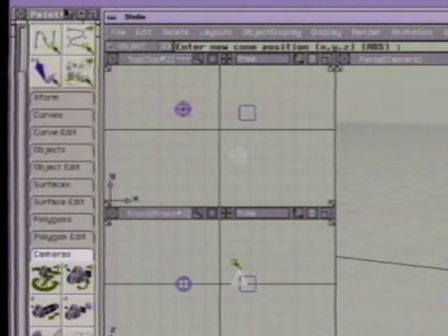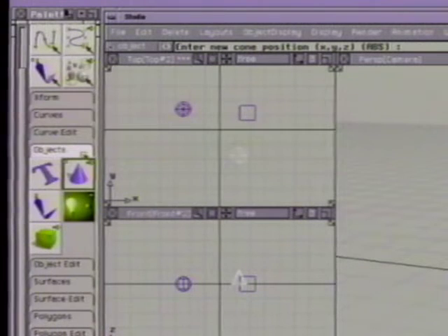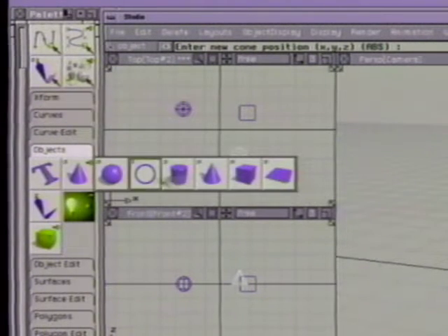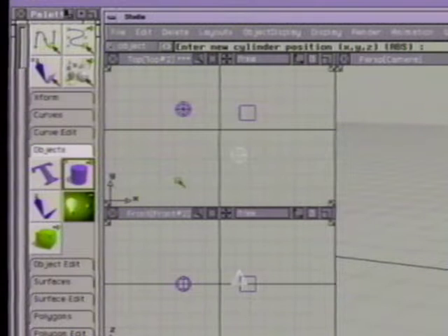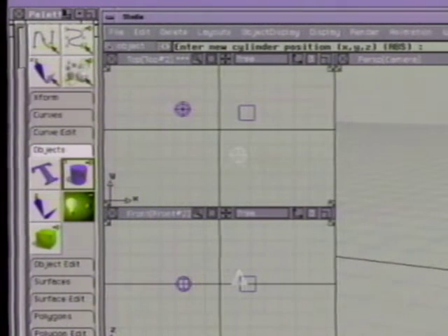As well as opening up an option box using the Tools menu, you can also double-click on the Tools icon. In the Tool palette, click on the Objects tab to reopen this section. Click and hold on the Primitives pop-up and then select the Cylinder tool. It should now be the top primitive tool in the palette.